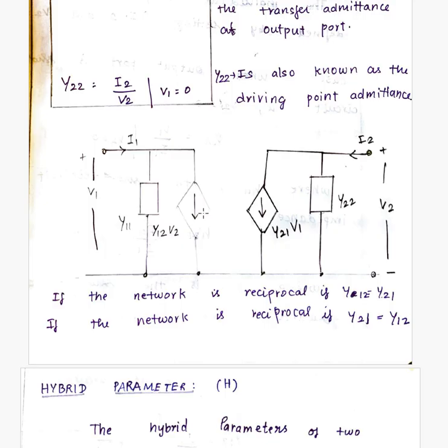And then the current source depends upon the output voltage, so here it is written as Y12 into V2. The input voltage is V1 and the input current is I1. This is for the output port. For the output port, the current source is Y21, which depends upon the voltage of the input port, so Y21 into V1. Here the parallel admittance value is connected. It is termed as Y22. For the output port, here we are having the voltage and current values as V2 and I2.